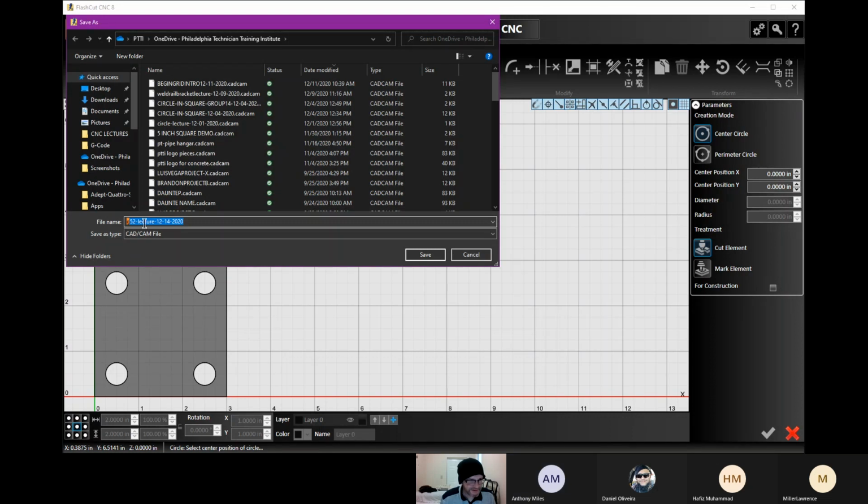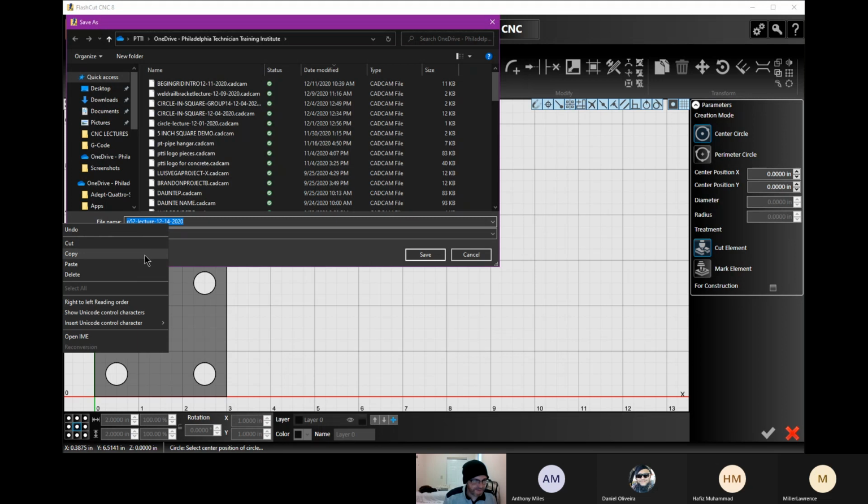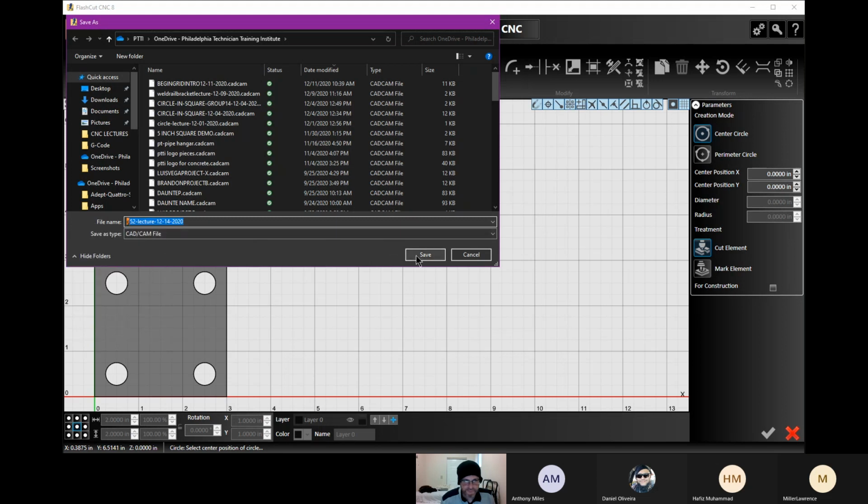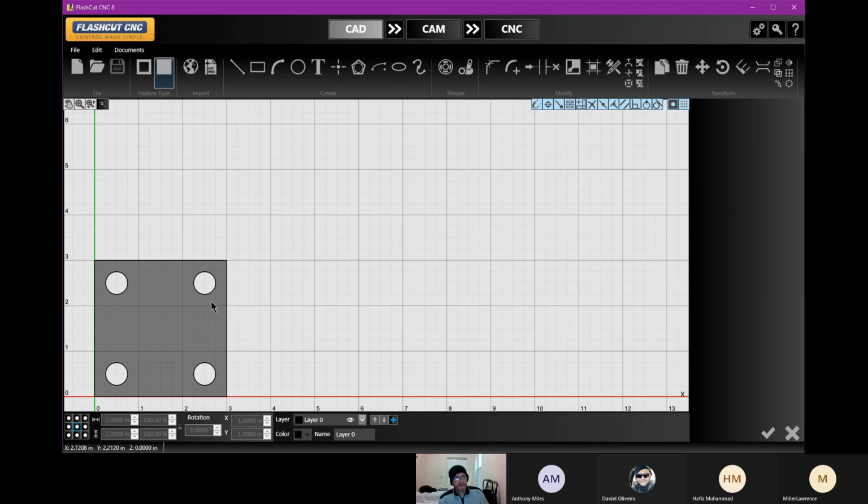We'll highlight this and save it so we can name our CNC file the same thing. Save. Okay. Now, since we are going to be using the G52 feature, we can actually leave this on top of the axis because we're going to use a system of local coordinates to move this around. Our first one's probably going to be like X 0.5, Y 0.5, just to get it out of the way of the axis.